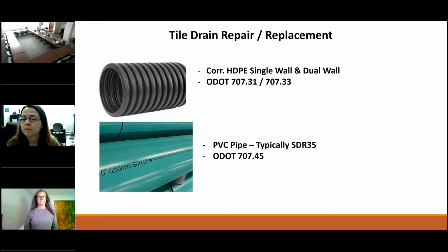The repair should be made, obviously, with proper couplings to ensure that you're making a good sound connection on that repair. I also know some other things that seem to help, such as a flap gate on the end of a pipe, and rodent guards or animal guards, which are significant ways of keeping some of the animals out of the pipe that like to sometimes build nests and pile up sticks inside the culvert or the drain tiles.